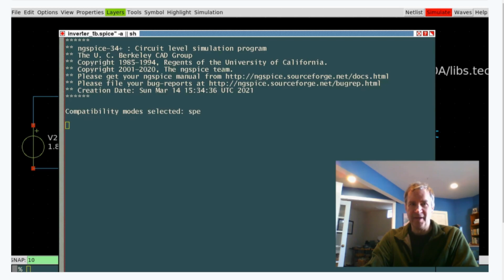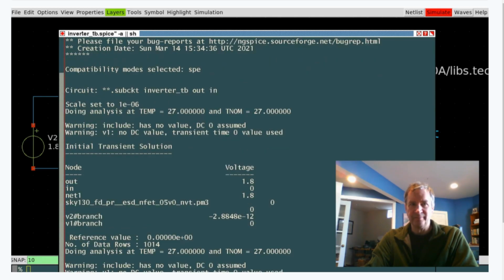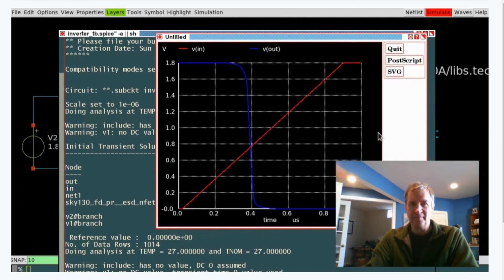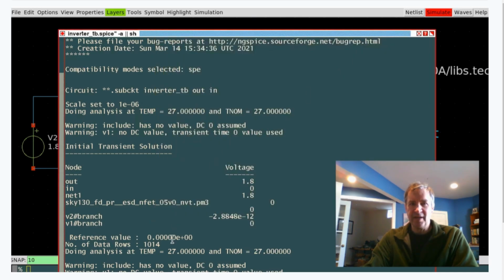And there it's moving ahead. And now it's done. And here's the plot. The lines should cross at about 0.8 volts. We wanted to display a plot, so we did not add the statement quit to the ngSpice control block in the schematic, so you'll have to exit the plot in ngSpice in turn. Don't exit Xschem just yet.